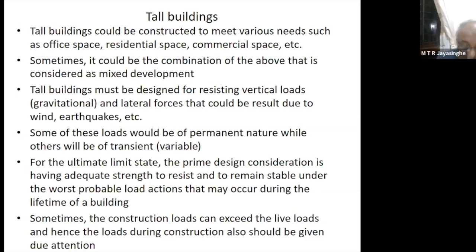because at the support, the maximum that can happen is there will be a plastic hinge forming at the support, and that plastic hinge will allow some rotation in the beam. With that rotation, more moment will be transferred to the span. So if a failure occurs, it will be in the span, not in the support. So that's why we allow moment redistribution when you are designing, knowing very well a beam will never ever fail at a support, but it will always fail in the span.